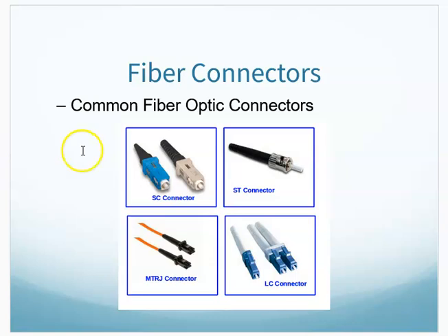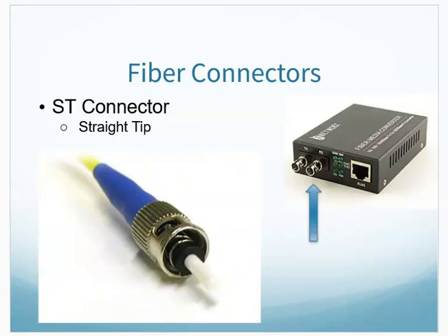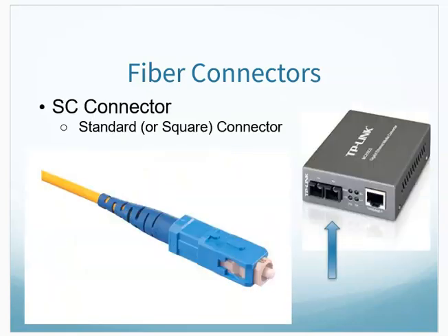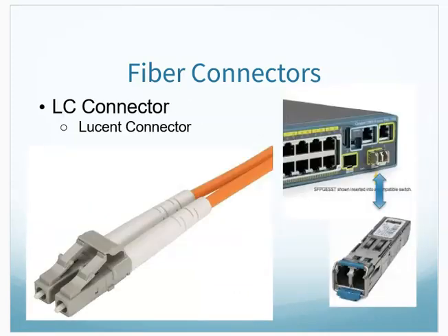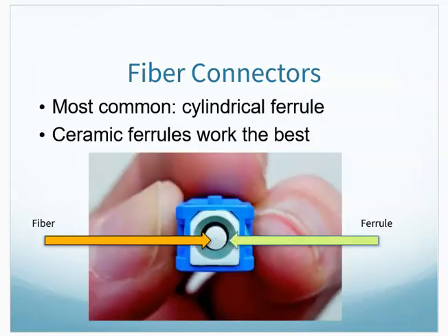Do remember there's different styles of connectors. Once upon a time, ST was very common. Then SC became much more common and used for quite a while. The most common one right now is your LC fiber here. The next couple slides, I have close-ups of each one so you can see them up close and personal. That way you can tell them apart. And then there's your LC fiber connection right there.